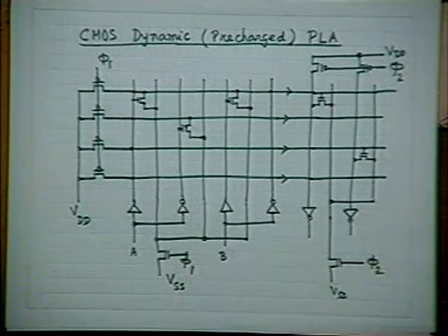And this is, of course, a very popular PLA now. Though we have studied the NMOS most, in fact, the actual PLAs are mostly implemented by CMOS technology today and not by NMOS technology. And people use this dynamic approach as indicated here. So if I ask in the examination, design a CMOS dynamic PLA with folding, etc., you have to do all these things. Only thing is you have to finally draw the circuit like this.